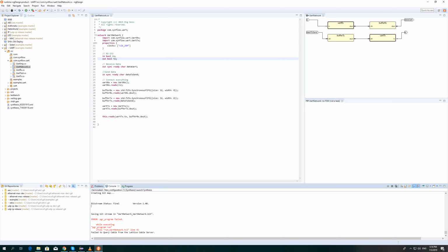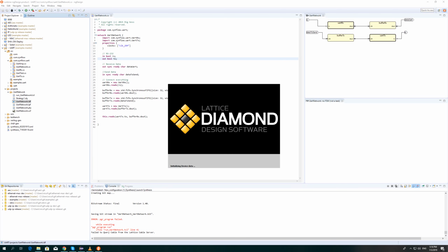So what has happened? The Synflow SDK has created a project for Lattice. It has executed the Lattice compiler and synthesizer. The Lattice compiler has created the bitmap, which is this file, and I can now use that bitmap to program my FPGA. But first, usually you want to assign the pins, and you want to add a FIFO or to set up your FPGA. So to do so, you can just click on Project, open the generated project.